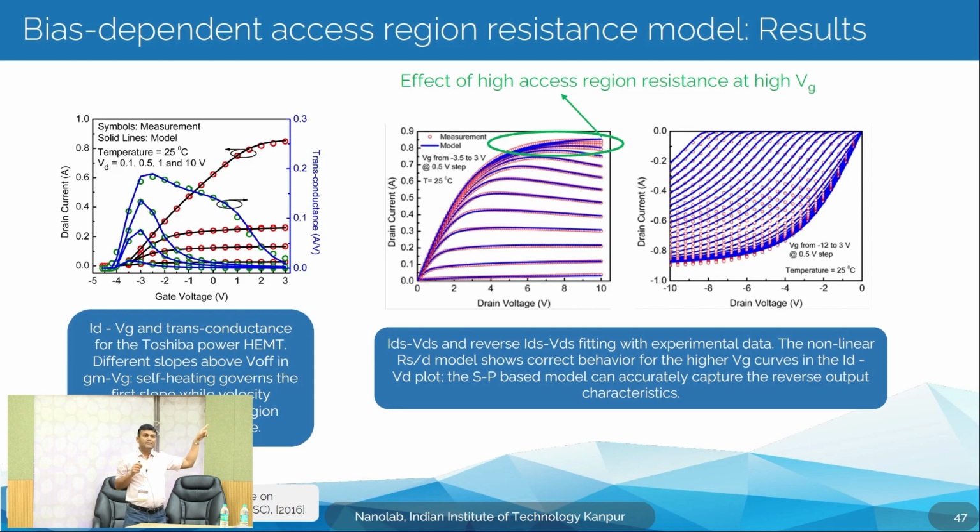This is very similar to the quasi saturation effect in LDMOS. And that is the reverse characteristic, since this device needs to work in both directions, with VD or VS opposite also. So, that is the reverse, and all of this is validated with the measured data.